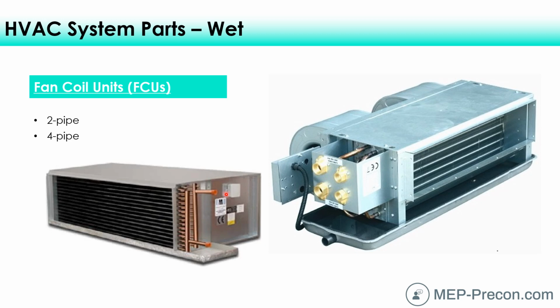And as you're probably imagining right now, the 4 pipes is where you'd have both a heating coil and a cooling coil. And so with the 4-pipe fan coil, you can provide heating or cooling year-round to a particular space. With a 2-pipe fan coil, you can only do one of them.